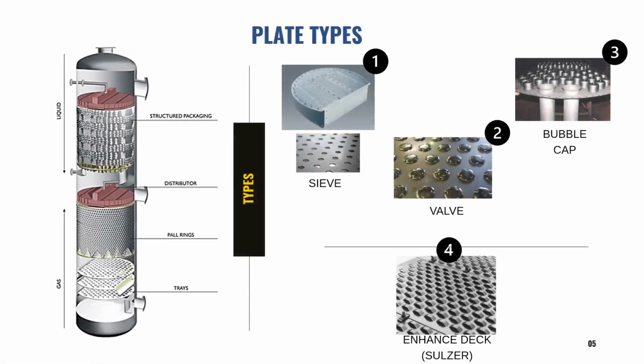Okay, so there are a few types of plates. The two types of plates used for a plate tower are the sieve plate and the valve or bubble cap. So if you see any process description using sieve, valve, or bubble cap, the process is actually referring to the plate tower. So the gas absorption process is occurring in the plate tower type of column.